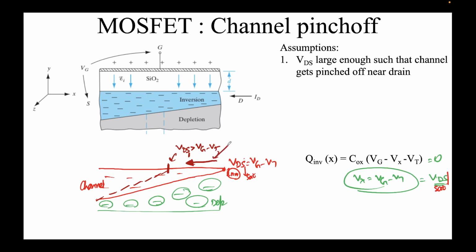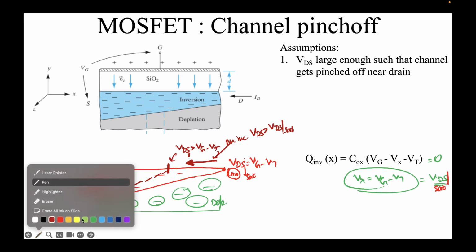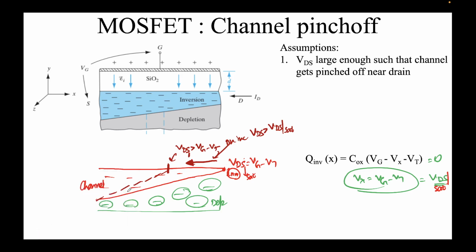This is happening on increasing VDS greater than VDS SAT. It will keep on shifting to the left, which I have shown over here. So you see the dashed line, the brown line, and below that, in that case, this will be the depletion region, even this will be the depletion region, everything this will be the depletion region. Okay, this means now we have even gone beyond pinch off. So this point that you see, VDS1, now we have even gone beyond the pinch off.